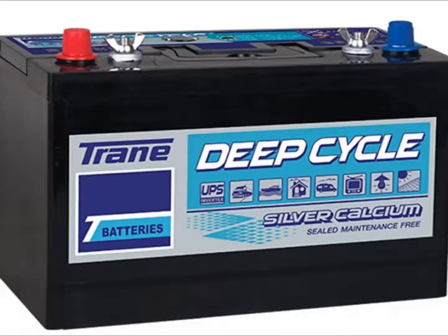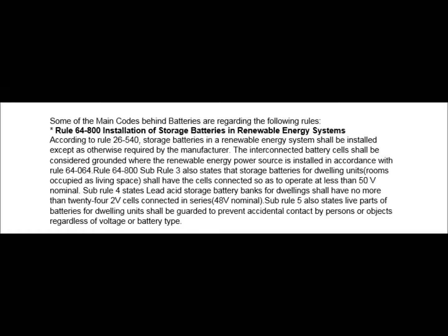Some of the main codes behind batteries are regarding the following rules. Rule 64-800, installation of storage batteries in renewable energy systems shall be installed except as otherwise required by the manufacturer. The interconnected battery cell shall be considered grounded where the renewable energy power source is installed in accordance with Rule 64-064. And Subrule 4 states that lead-acid storage battery banks for dwellings shall have no more than 24 2-volt cells connected in series, 48-volt nominal.